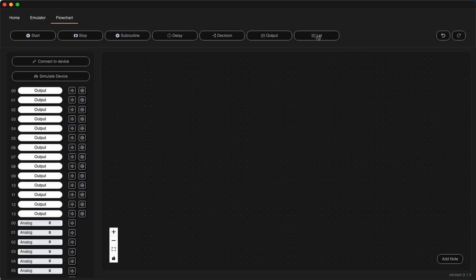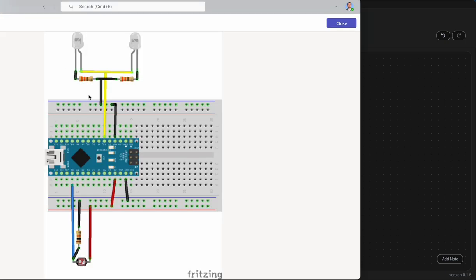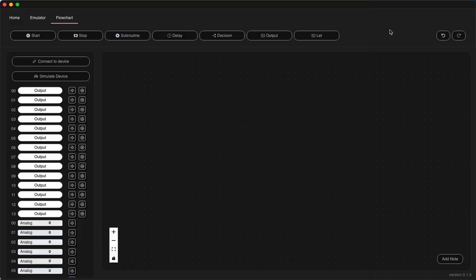We're probably not going to play with this one just yet, but let's get in and have a look at how we can make our nice basic LED LDR work here. If we remember, there's our circuit. We've got A0 attached to our LDR, and we've got D3 attached through here. So they're the two key things that we need over here. We come back over into our output. So that's happy, we've got that one set up.